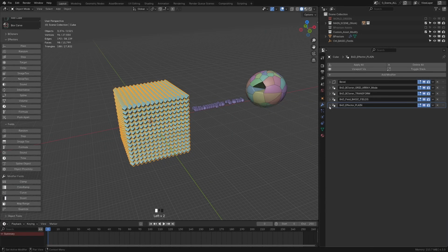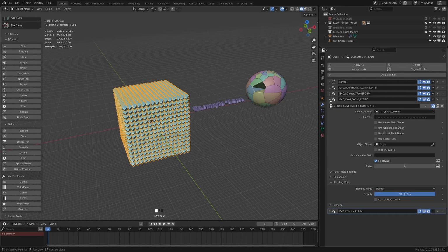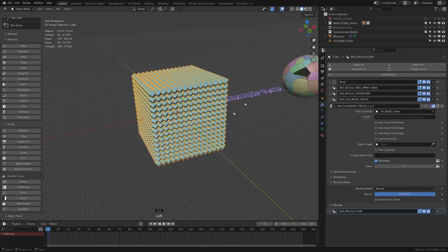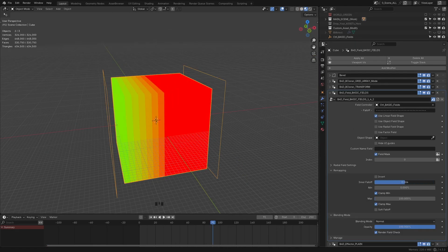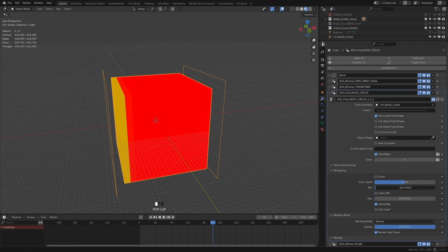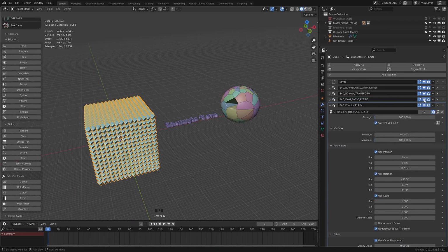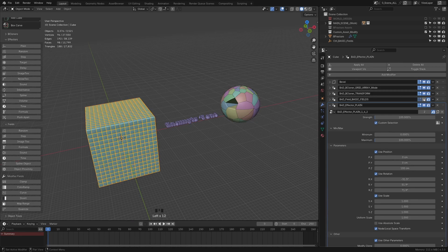When you add any effector, the add-on automatically adds the field called Basic Fields. This field is necessary for the correct work of any effector, and it has the basic and common parameters of most of the fields. The fields allow us to generate a fall-off to control how the effector affects all instances. With the field it is really easy to have all control over the instances. By default the fall-off is infinity, so the effector affects all instances equally.